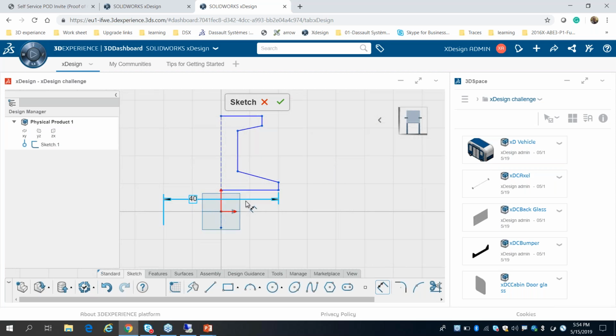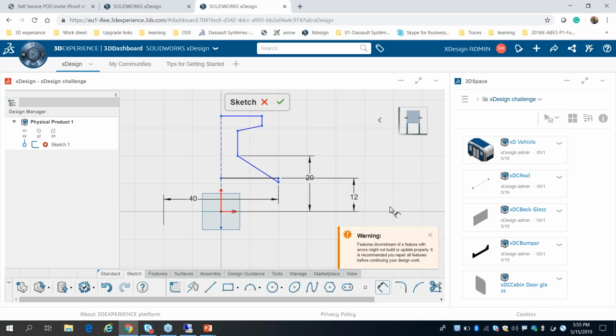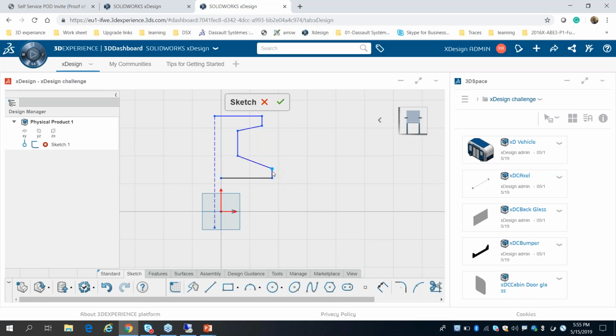The first entered dimension will be the readjustment of your complete sketch. If you observed, previously while I was selecting it, it showed me a dimension around 150, and right now it is showing me a dimension around 40. So all the dimensions and the whole sketch get readjusted according to it. So make sure you have chosen the correct dimension while you are creating the first dimension, so that your sketch is properly converted. You can then manually adjust your sketch.